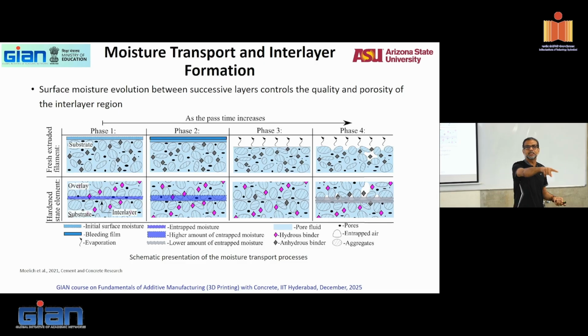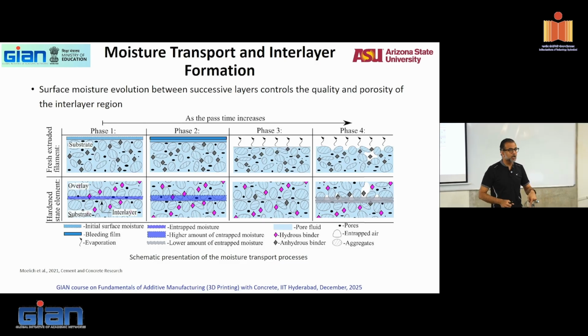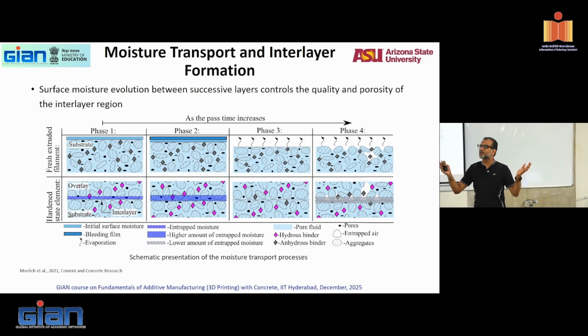Robotic arms also have a limited path of activity. You can control that better. But when you do gantries, these gantries are probably 10 meters long and 10 meters wide. They're on a rail, so they keep on putting material in. When will I come back and put on top of it if I don't know? And if I don't know the properties of the material that are developing, I will invariably end up with cold joints. Think about 10 layers or 20 layers you're constructing, layer after layer after layer, if it's a cold joint, right? That is a massive problem when you have larger constructions, when you do very large prints.